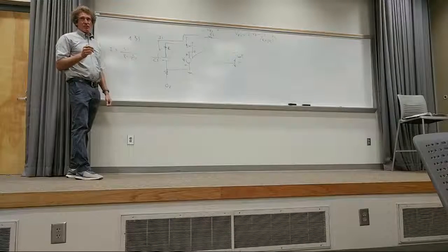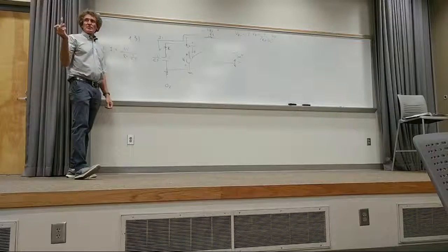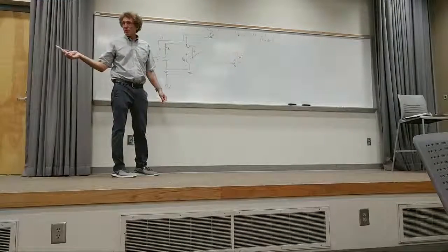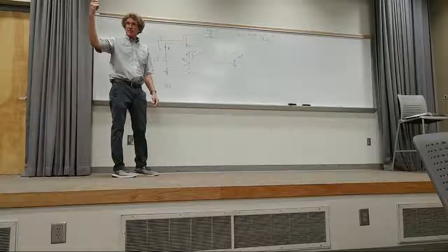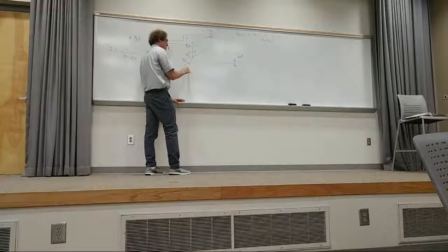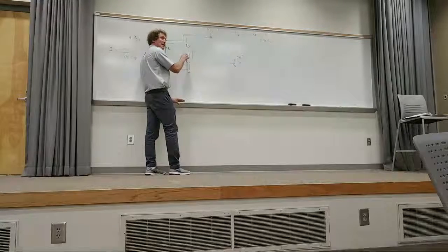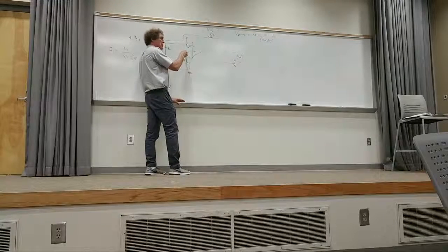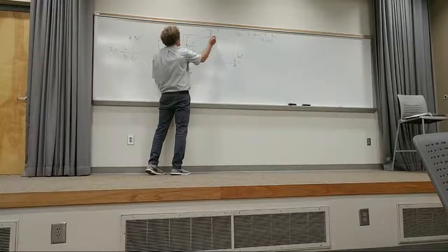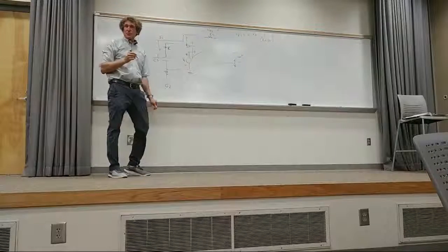Here's where you need to be careful. When I used to teach circuits, I said, whenever you want the voltage between 2 points, you start at the negative terminal with respect to the voltage you want. I start here. I go around, this is a voltage increase, right? An increase of V1. Do y'all see that here, class? Increase of V1, and this is a voltage increase of VR2, correct, class?